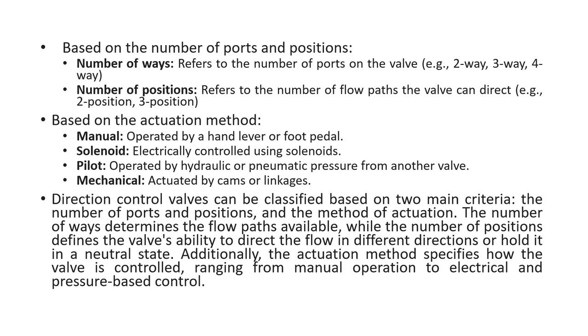At the cylinder ports A and B, when pressurized fluid enters the port B, retraction of the cylinder takes place through the direction control valve, and the oil which is in port A returns to the tank line. According to these ports and positions, direction control valves are classified.